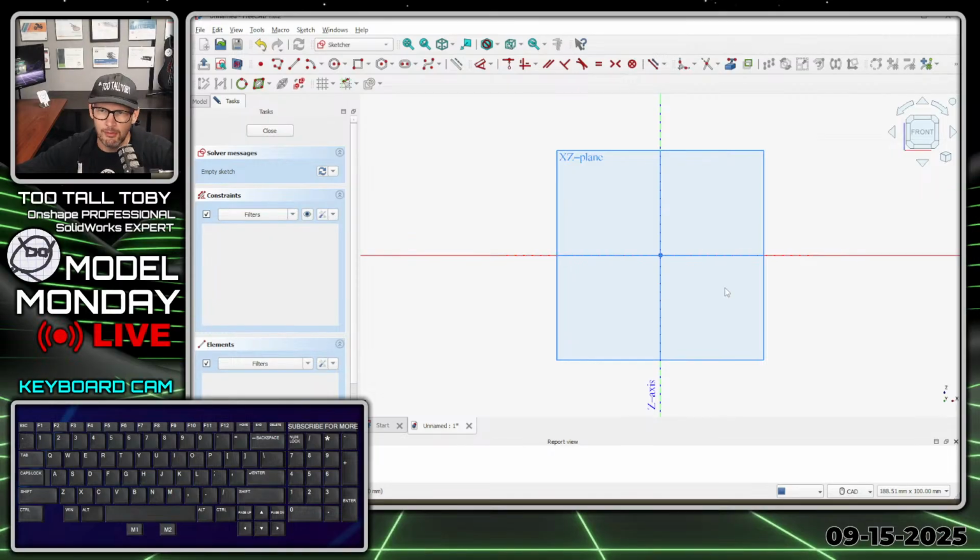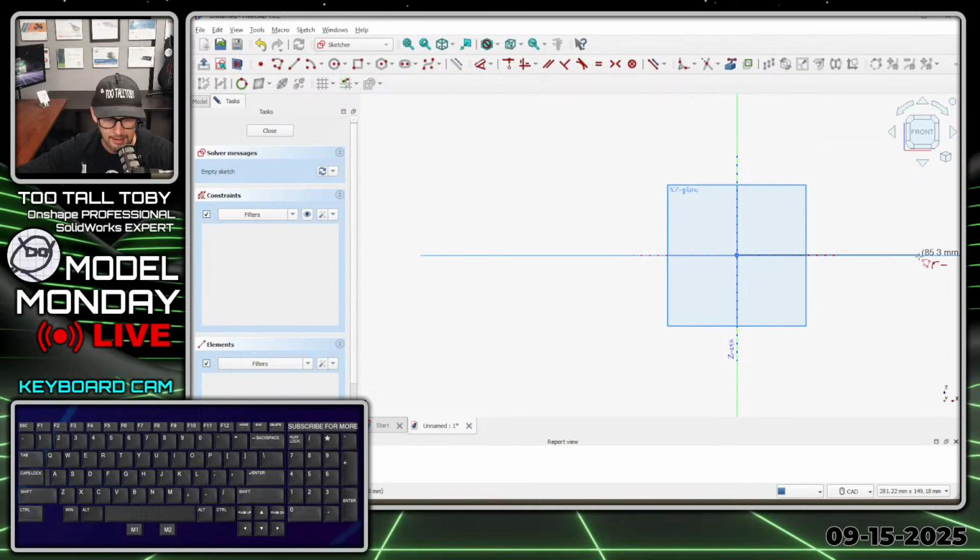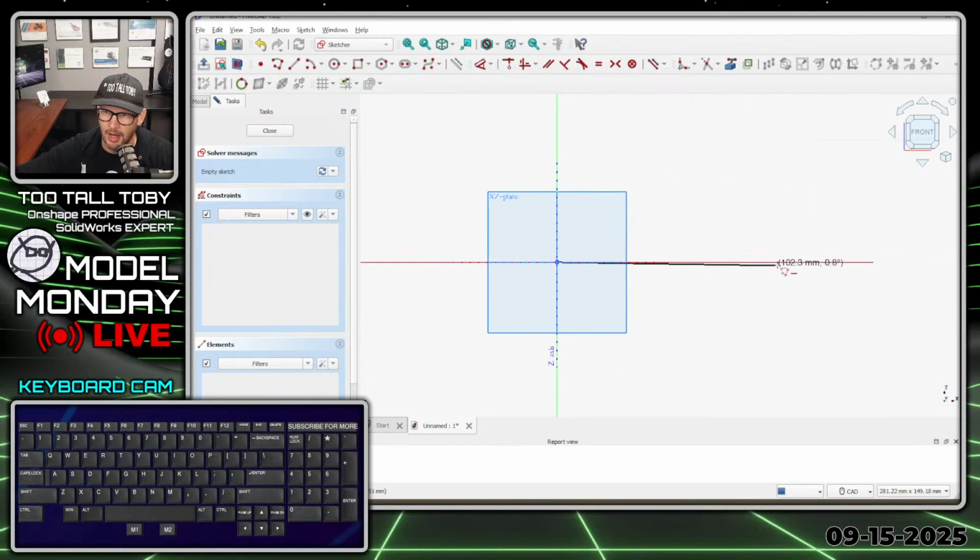But here you can see that following my game plan, I'm going to start out with the polyline command in FreeCAD, and then I'm going to single click here on the origin, move over, and sketch the geometry for that deck. So this is going to come over to about 90 millimeters, give or take. Looks like it's about 90, a little bit short, probably closer to 85.